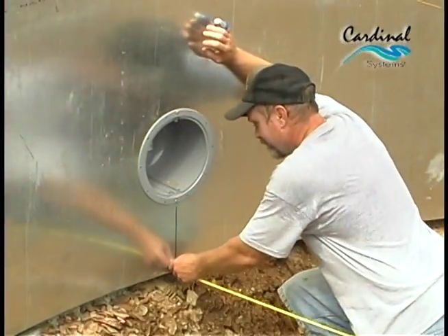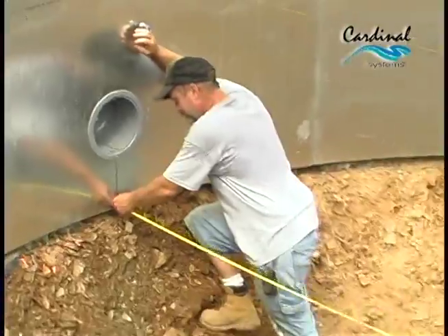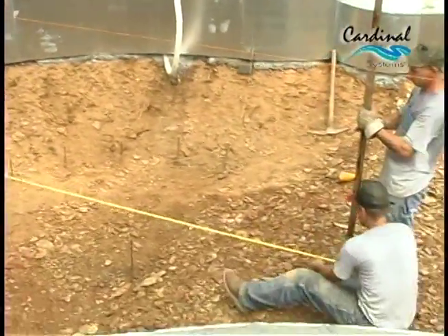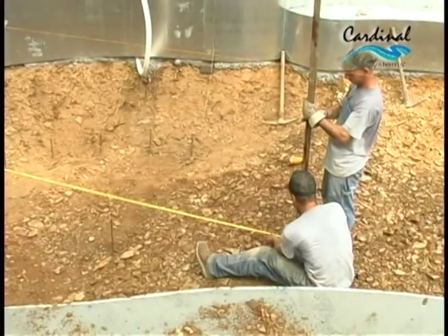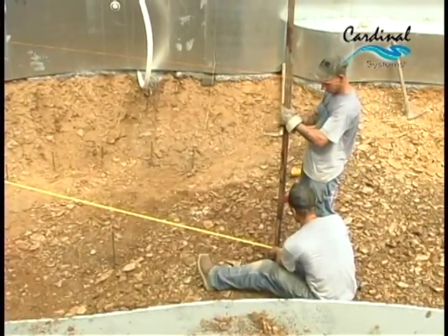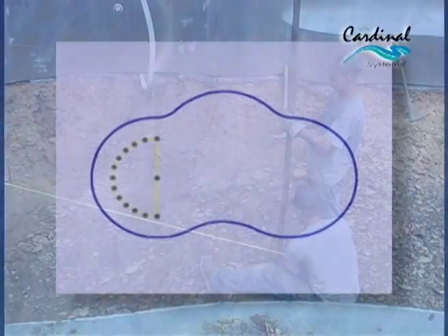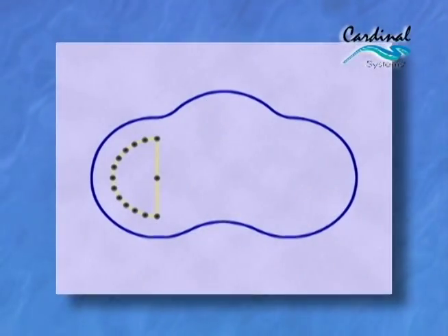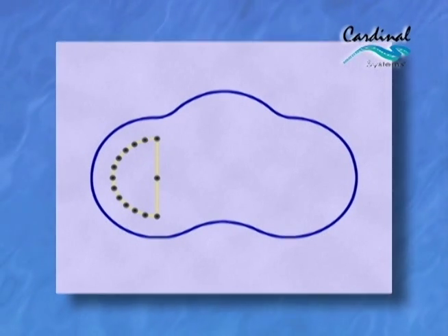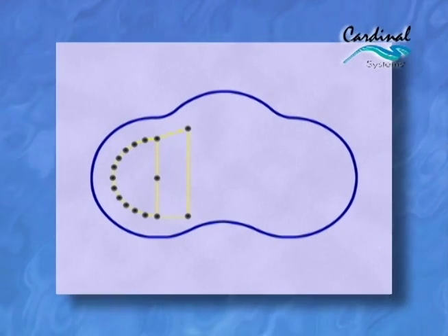To establish the point where the second level slopes to the hopper, run a tape 13 feet 6 inches from the center point under the main light, and use the identical technique to stake out the center of the break point. From that point, you can establish the break point on both sides and stake them out with rebar, measuring for the concrete float depth and stringing out the slope to the hopper. Use this technique to find, stake out, measure, and string the second level.